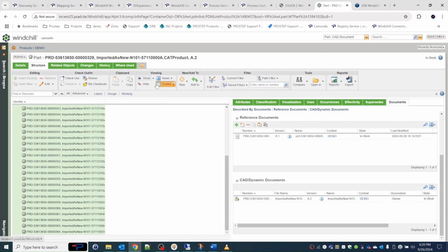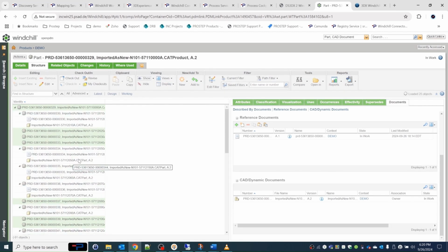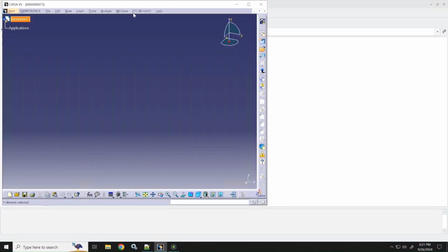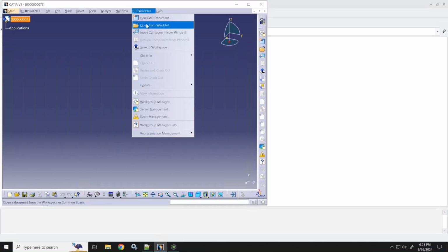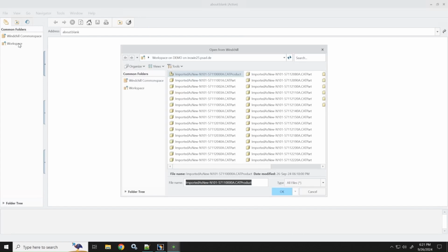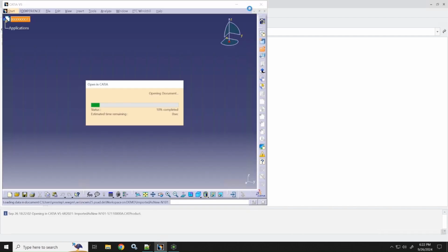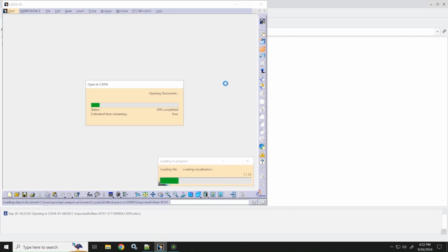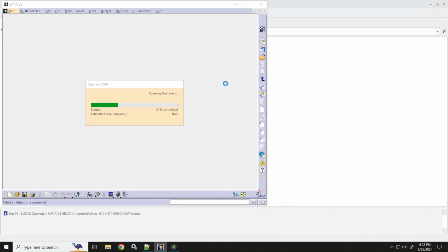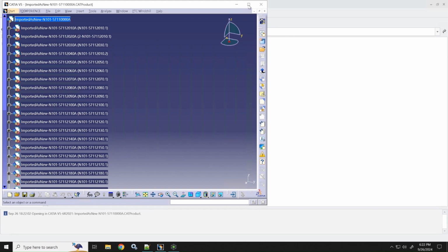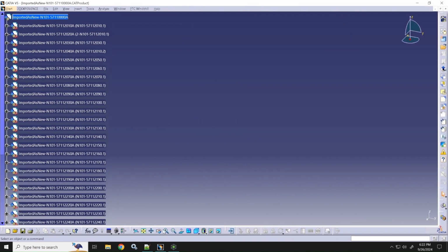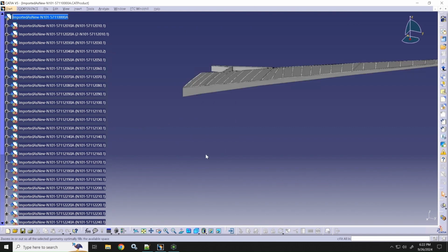We can then also open that up in CATIA, so we can expand it all. You can see that there's the STEP data that's associated there, and then also CATIA data. So we go to our Workgroup Manager, and then we can load that same file in CATIA, and then you can see it populate the wing assembly here. This is downsave from CATIA V5, but we've also brought in STEP 242 data, just so that we have a comprehensive data set to show different options in how you can synchronize data between these different environments.